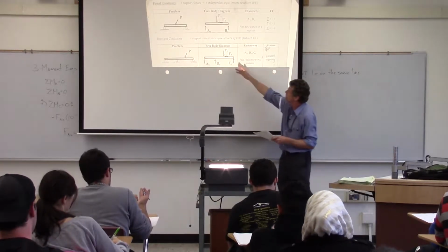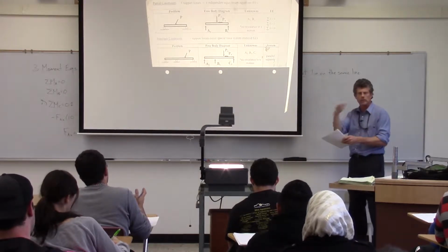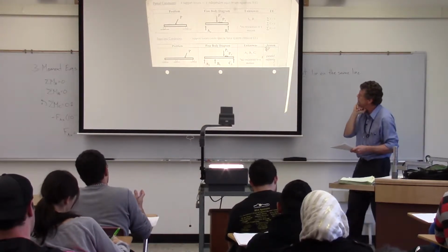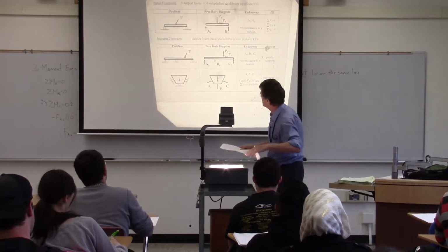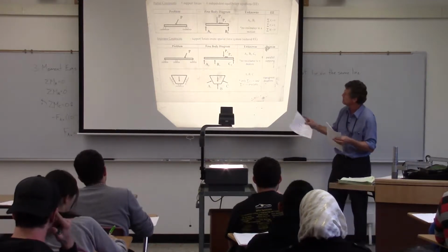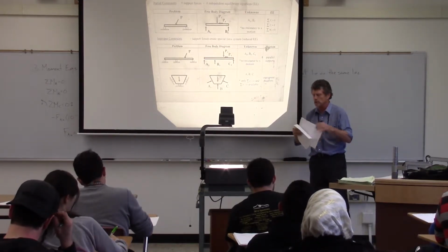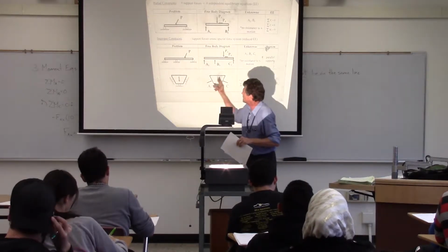We don't have the ability to solve for that x direction there, and the thing will be a skateboard, basically. It'll just start taking off on us. And the other one that's a little harder to visualize most of the time is what we call the concurrent supports. And this is something that they actually experience a lot in dry docks. They dock a boat and that sort of thing, and it's got a weight there.